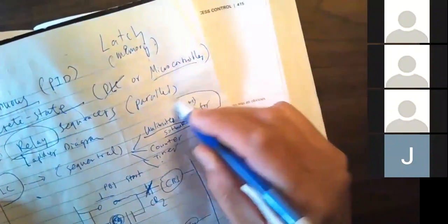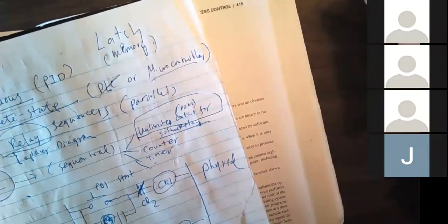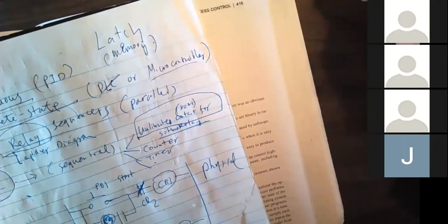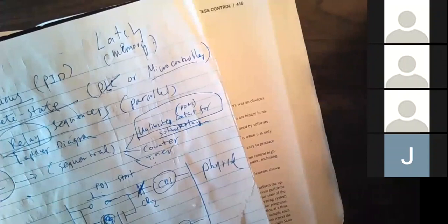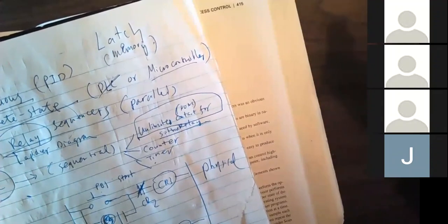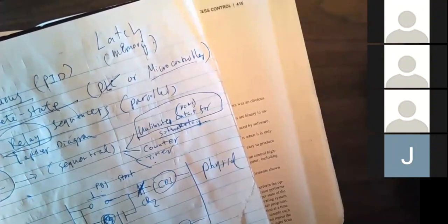Not only do we have a limited relay, also PLC can have unlimited relays. In theory, it's limited, but it's almost unlimited. For example, if an assembly line needs 20 relays, you have to physically buy 20 relays. But a PLC, by using software to simulate relays, we can just add code, add relay modules, relay software. So we can have 100 relays, we can have 200 relays, just one PLC. You need 200 relays, you just put in a new code.